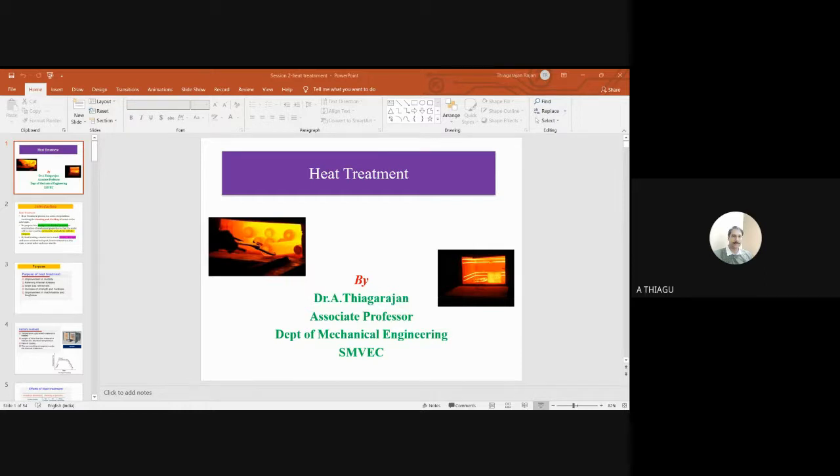So what is the molten metal used for the cyaniding process? Sodium cyanide and sodium carbonate, both, and the steel should be heated to 950 degrees centigrade. During this treatment, both carbon and nitrogen are deposited on the surface of the steel. These are the applications where I can prefer the cyaniding process: most of the brakes, cams, springs, shafts are applicable for cyaniding.